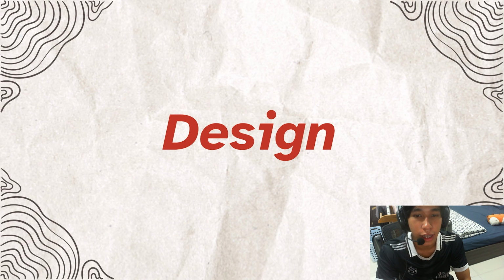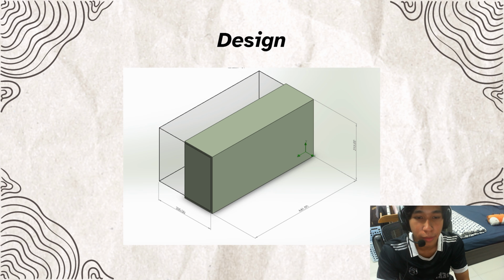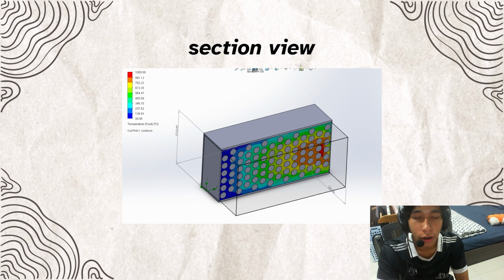I will talk about the design of our air heater. So here we can see the dimensions of our air heater with a length of 641.5 millimeters and a height of 315 millimeters. And the thickness of it is 330 millimeters in order to fit in the two bundles inside. Here's a section view of our air heater with a bit of simulation, and we can see the temperature as well. So along the horizontal direction, we have 14 tubes, and along the vertical direction, we have 6 tubes.